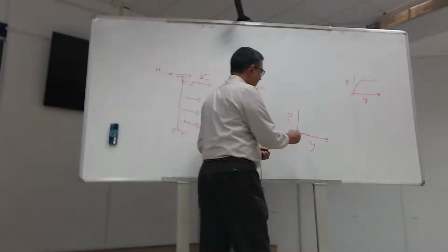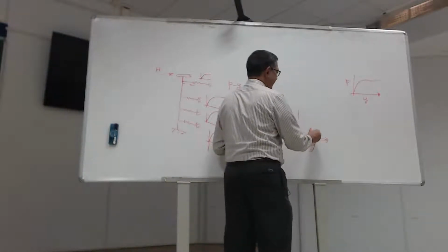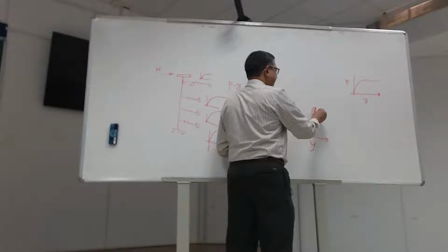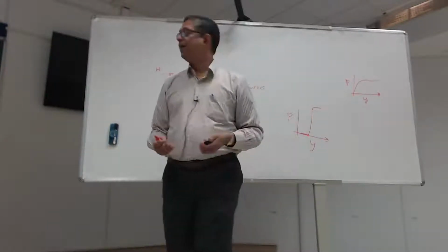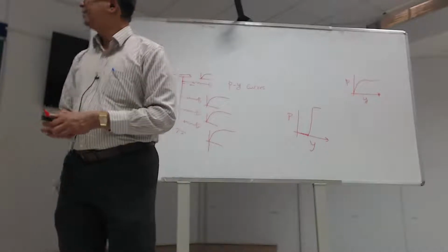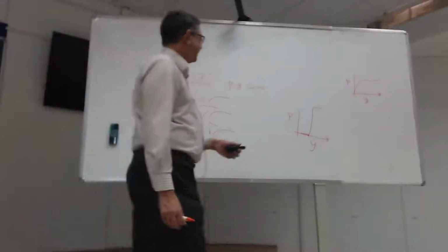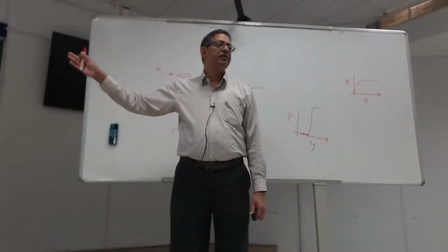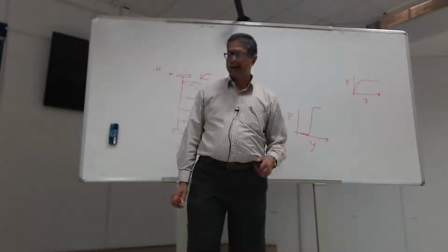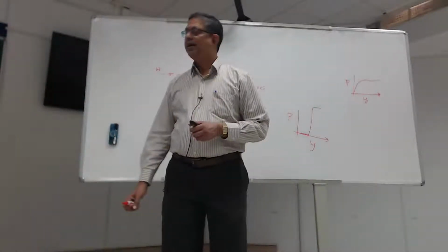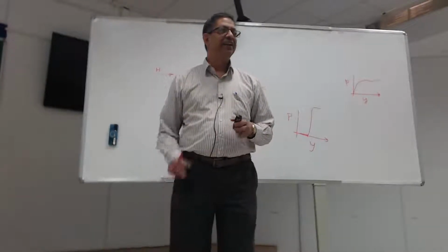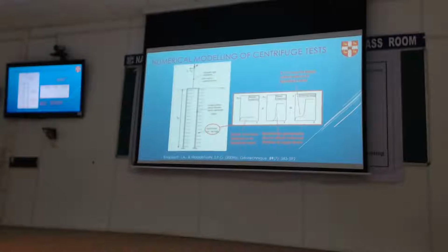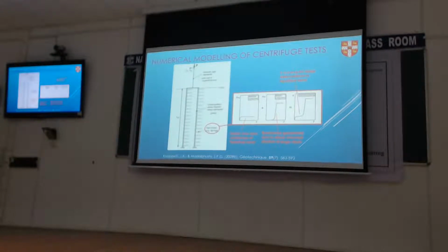Once the soil dilation kicks in, I will get a big resistance until a limit is reached, where the soil can't hold any more suction. So that's represented by this, where the rate is now offset from zero, but is quite sharp. If I join these two together, I'll get that, which is what we're looking for. So we want a spring which is soft at the beginning, plateaus out, and then kicks up with the dilation again.